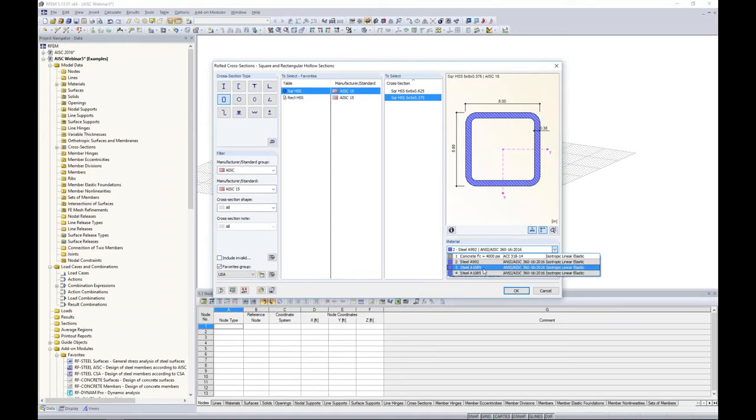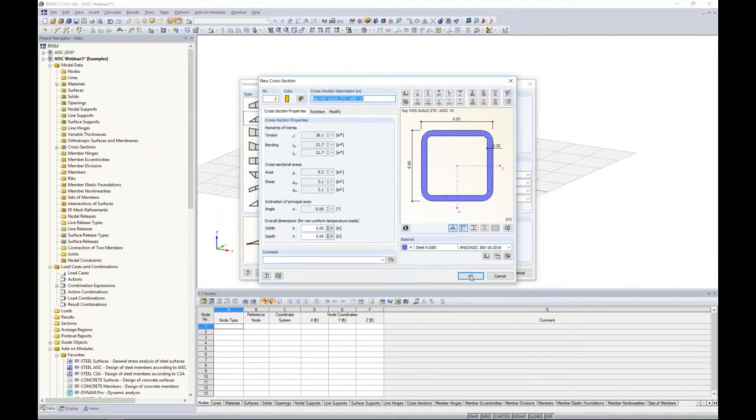You can see I accidentally entered it in twice here, no problem. We'll select the fourth material here, 1085. That will always be available now when I go to draw a new member because I've defined that material within this particular file. And I click OK.